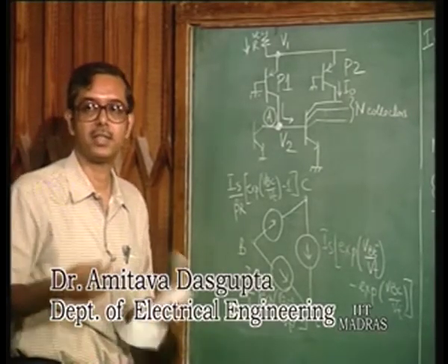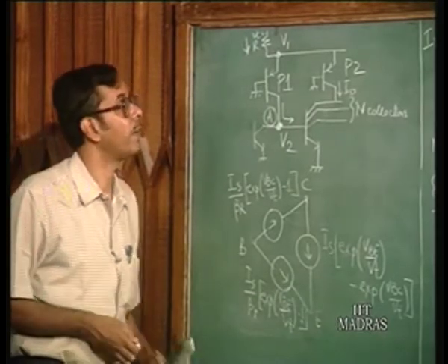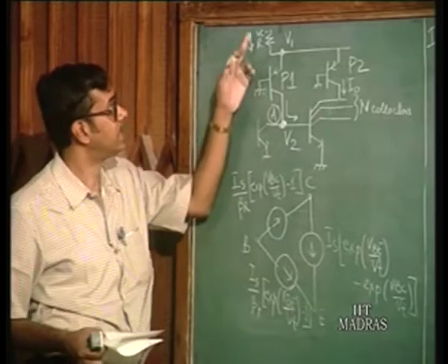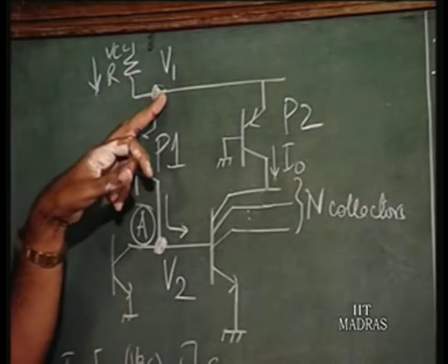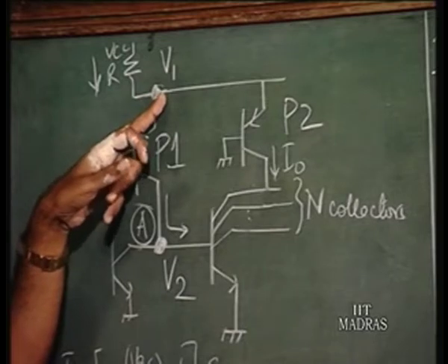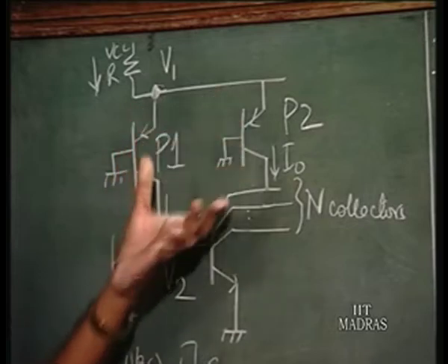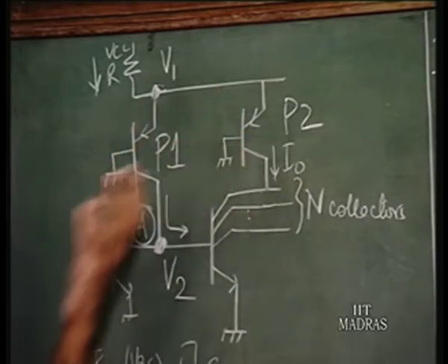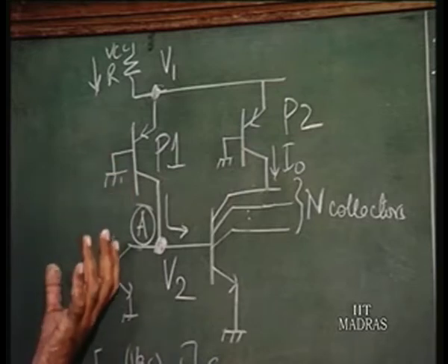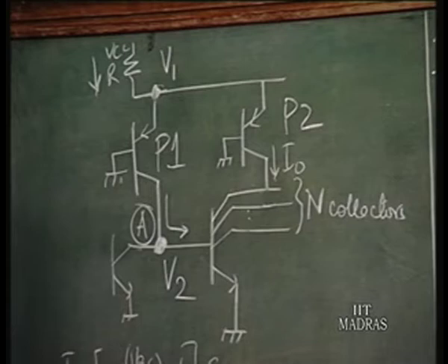So, again there is a trade off between noise margin and power dissipation. If you increase the current flowing into the cell, that is if you reduce R, because this voltage is around 0.7 to 0.8 volts, you have larger current, which would mean that there is going to be a proportional increase of current flowing through the individual injectors. So, that is going to improve the noise margin.